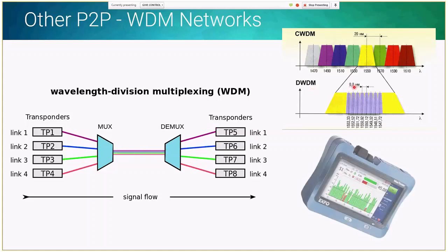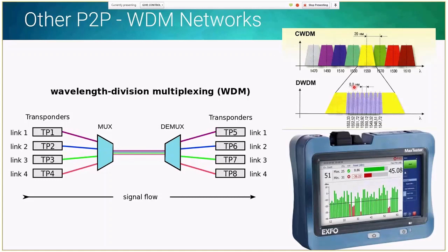Just to give you an idea, in terms of troubleshooting of DWDM and WDM networks, because the spacing and the channels are specified by the ITU-T, these channels can be verified using, for example, an instrument called an optical channel checker, which gives you the indication that on the same fiber you can measure all these different powers that you can see here on the screen.